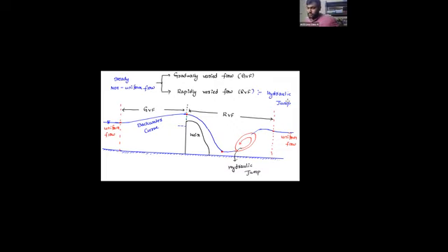So I hope you understood. This is a practical approach. What is happening on the upstream side of a dam? This is the upstream side, and this is going to be the downstream side of a dam. So when does the flow start? Like uniform, and due to obstruction, water level rises. It is a GVF, and once you open the gate, whatever the fall, here there is a sudden change. If the variation happens over a small span or short span, then you can call it a rapidly varied flow. So I hope you can understand.